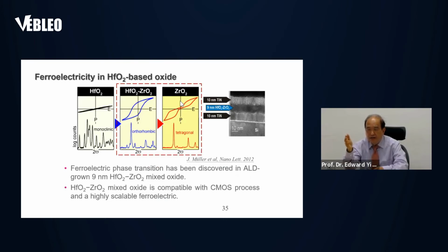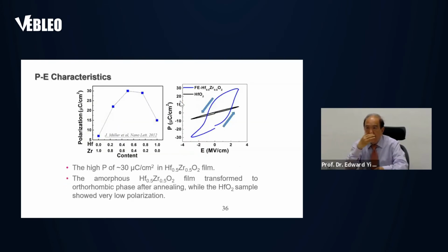And the way you do it is use hafnium nickel oxide as a ferroelectric material, and you can see that in the center, if it's not a combination, just hafnium oxide or nickel oxide, they would not have this kind of ferroelectric effect. Okay, they don't have this polarization. And you can see that the polarization is highest when the hafnium nickel oxide is 50%.